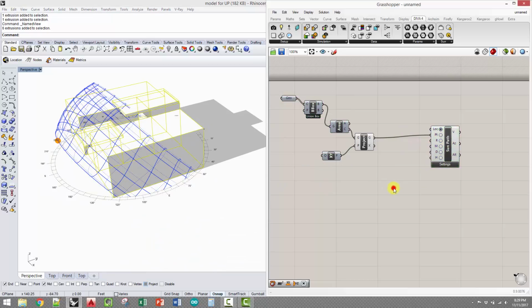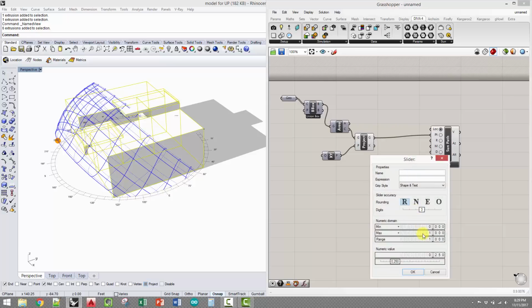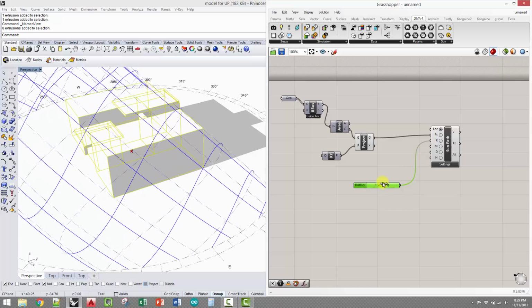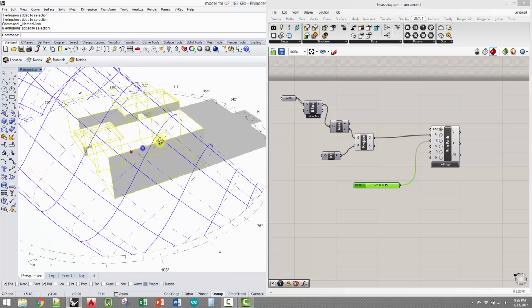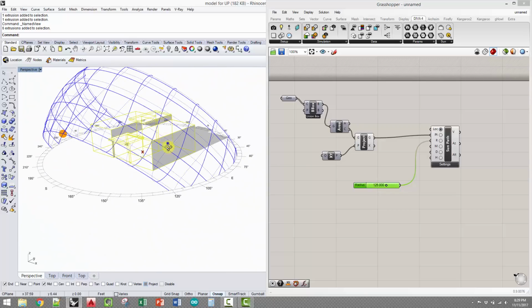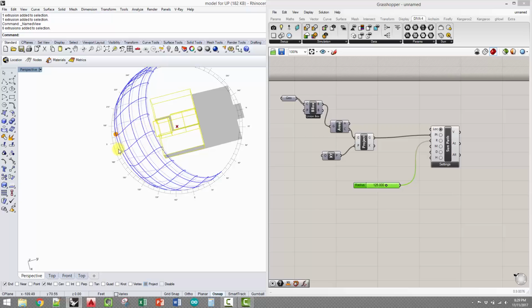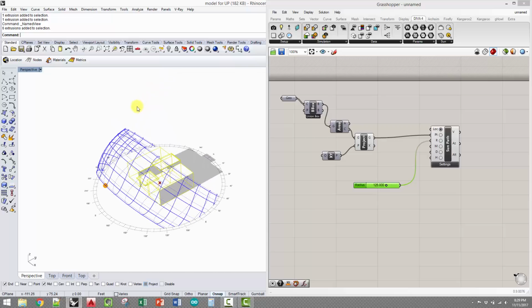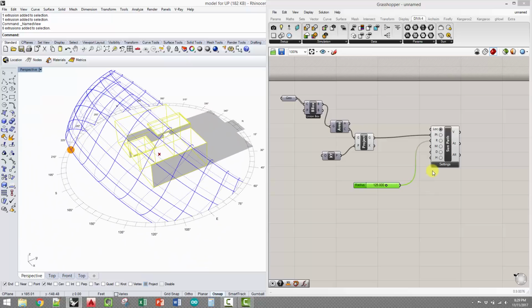And then for the sun path, I'm going to do a radius. So I need a number slider. Make this fairly large because I don't know what I'm going to need yet. And you plug it in, and the radius is the size of the whole shebang here. I've found that for this model, maybe 125 units seems to be fine. Just big enough. You want to get it to the size of the shadow, and take that into the diameter of it. It's also to create the diagram and make sure you have this solar angle. Okay, so I got that.